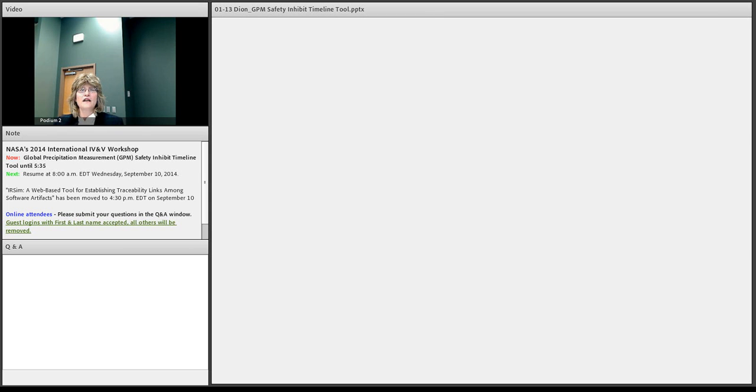And the next one is the RF transmitter. And the philosophy for the RF transmitter is that either you have the hat coupler on while you transmit, or basically you have the inhibits in place. So you see an alternation between red inhibits here and green, and red here and green up there. The only exception to that would be during EMI testing, when you need the hat coupler removed and you need to remove the electrical inhibits to do the testing. But in that case, you have a keep-out zone, which is basically containment of your RF during that testing.